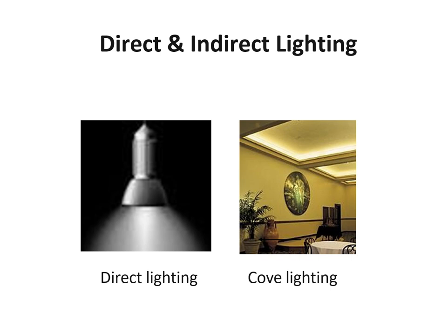Okay, examples of direct and indirect lighting. Direct lighting, as the name suggests, is where the light fixture itself casts light on the area it is focusing on. Indirect lighting, for example, when you look at the cove lighting example, you notice that the LED light is projecting on a wall or a ceiling surface, and it doesn't project directly on the dining table or the stage. In this kind of setup, indirect lighting is usually used to create a certain ambience, and then there's direct lighting shining on the stage and the dining tables.